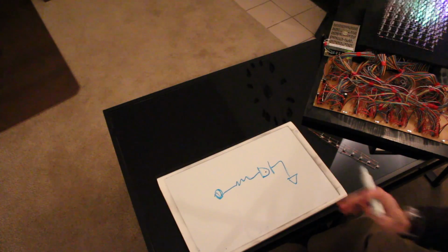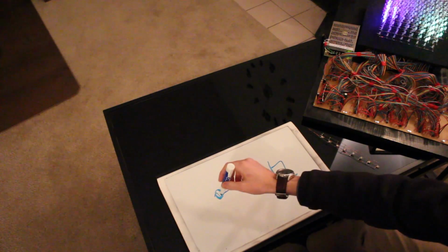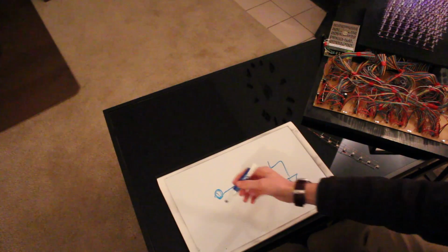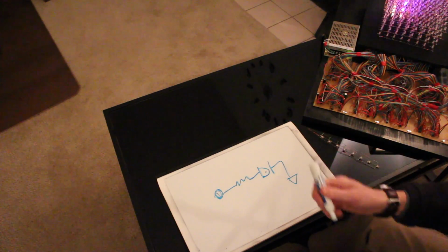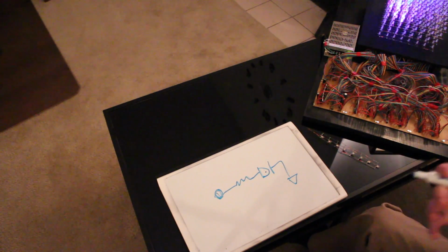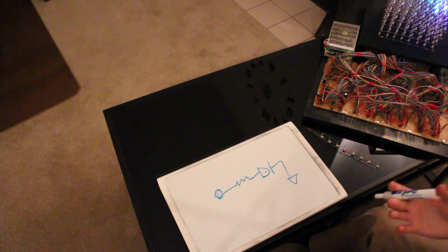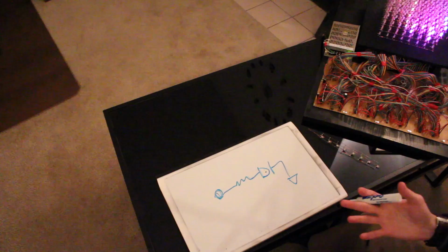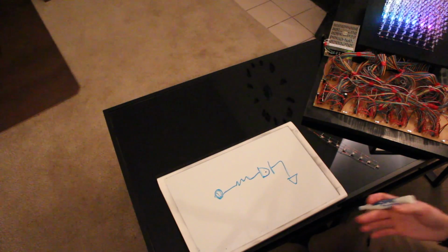Basically, you would connect this pin to one of the PWM outputs of the Arduino, and you write to it by doing something like an analog write. And you can do a value from 0 to 255, and it's 255 because it's 8-bit PWM.